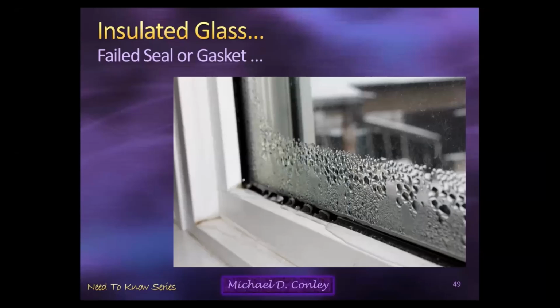It's going to require either the whole window to be replaced, or door if that's the case. I've heard of a company outside my market area, I think they're located in Tampa, where they can come in and drill with a diamond bit. They drill a hole somewhere in one of the panes, usually the inside pane, and then they introduce a desiccant into the inner and outer panes, which absorbs this moisture. I don't know if they're still around, but they were around a few years ago, and they were making good money doing this. I'm not sure what the quality of that is or how long it lasts, but that was a way to get away from having to replace the whole window.